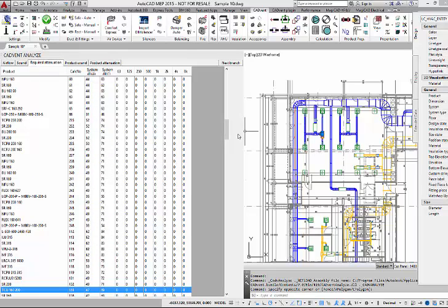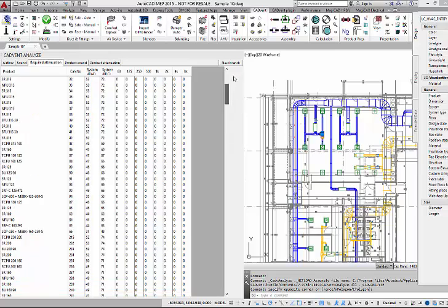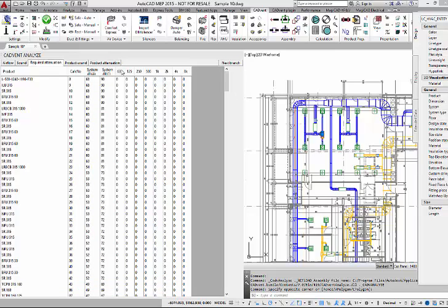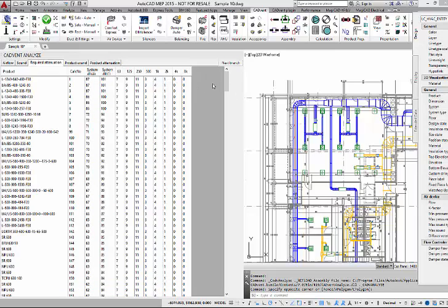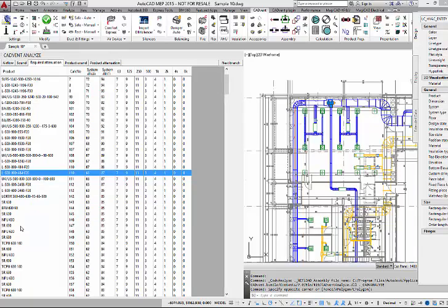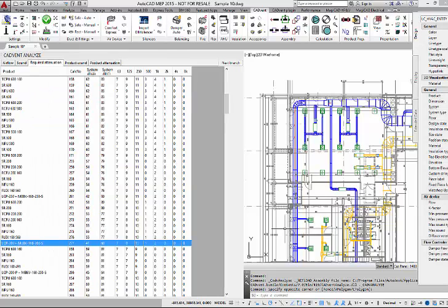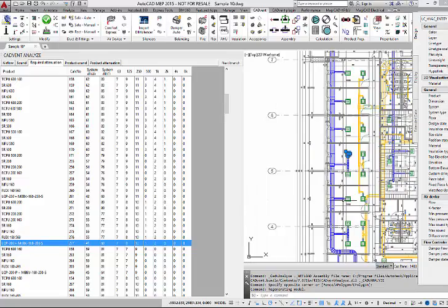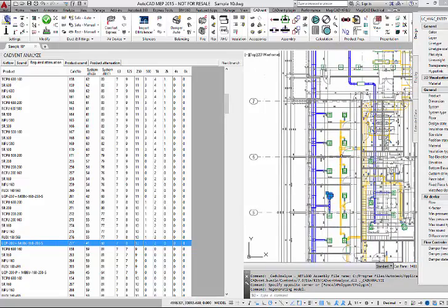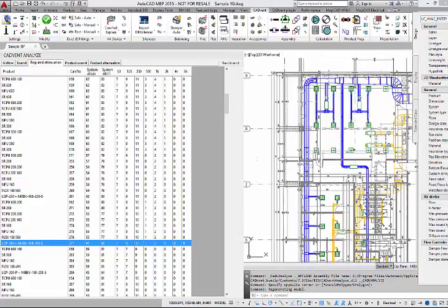So if I search now for the points where we have an attenuation requirement, so let's turn it like this, we see these areas here are with sound requirements. Then I can see also immediately the devices here, searching for that. For example, here we have a device. I make a double click in the table and it will automatically jump to that device. So in this area, we have a sound problem, and I guess it is the area here.